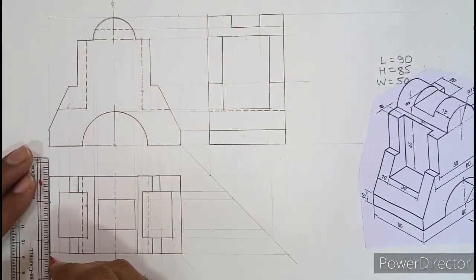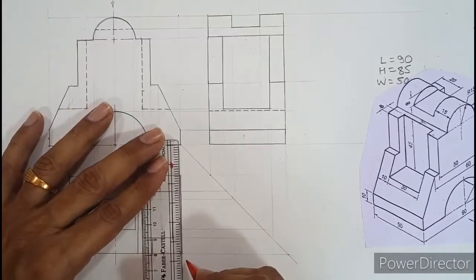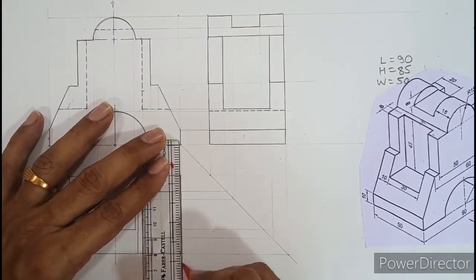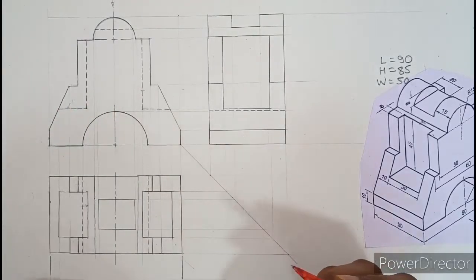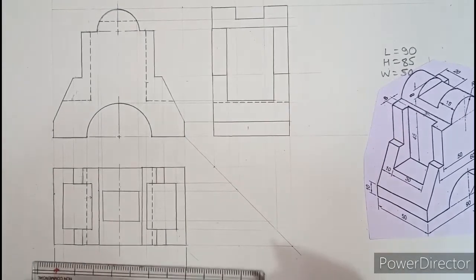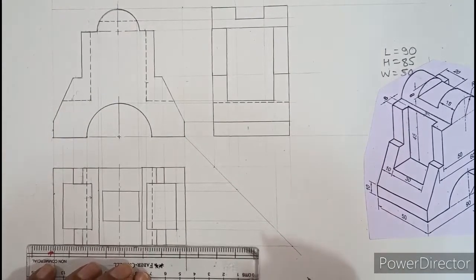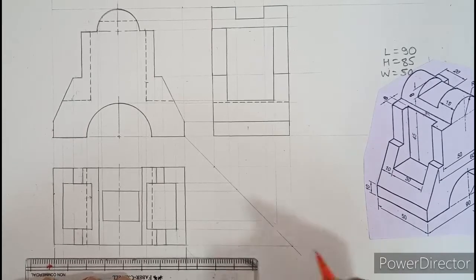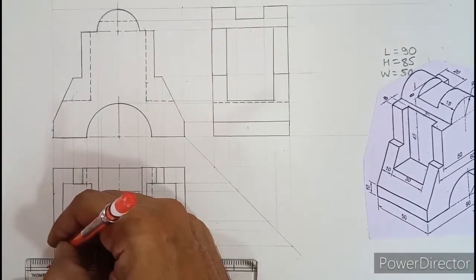From here we'll leave a gap of 2 millimeter and draw a medium dark extension line. I hope all of you know by this time why we should leave a gap. The gap is left so that you can understand the difference between object line and imaginary line. And from here, a medium dark line,